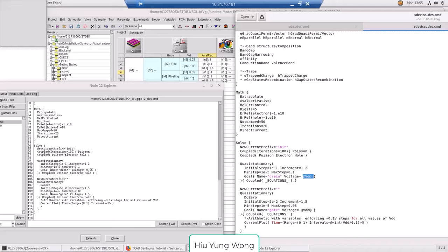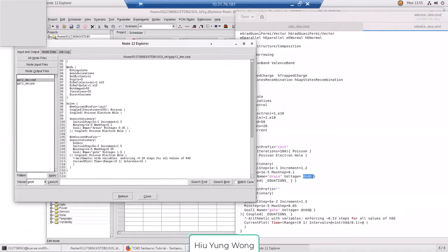Okay, is this okay? So is this how you come up with the characteristics, like IV characteristics? There are a few things, right? For IV characteristic, for example, you run the IDVG. You change the gate voltage and try to see what is the drain current, right? But you can have different drain bias. Drain can be at 0.1 volt, 10 volt, 100 volt, right?